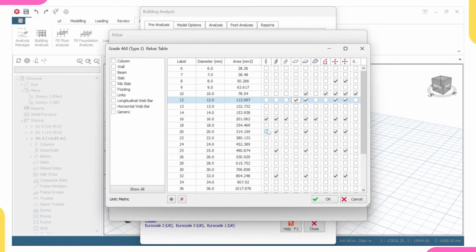So for me, there's no need of doing 16 and 20, or else I'm doing all this high-rise design that I'll not be doing 16 and 20 because I know that the client will be able to afford 20. So if I'm carrying out a duplex design now, I'm having Y20 in my reinforcement. If I submit my structural detailing or my BOQ, the client might not even look at my work set because he's seeing Y20, saying but other duplexes are Y16. So that's why I don't normally like checking Y20.